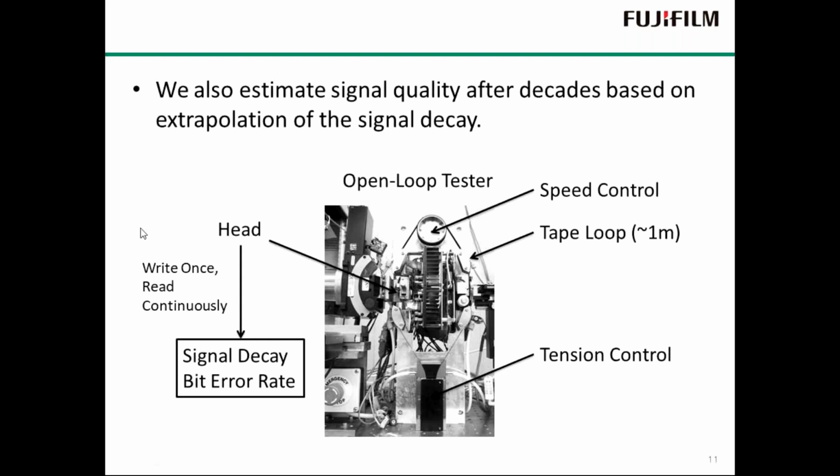In addition, we also have the actual read write head here. In this test, we write data once and read the data continuously, and measure the signal quality and signal decay. We also measure bit error rate.